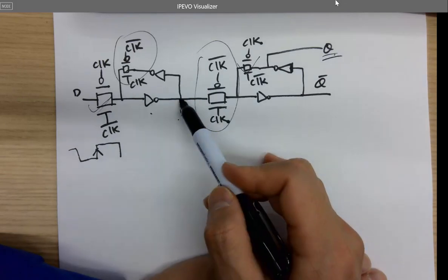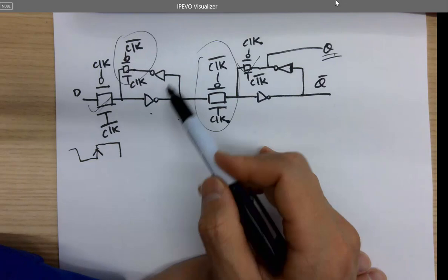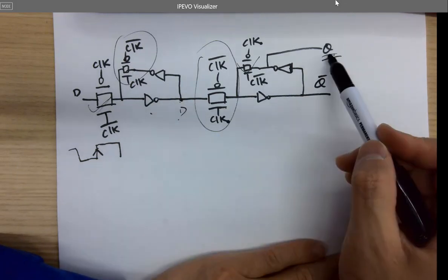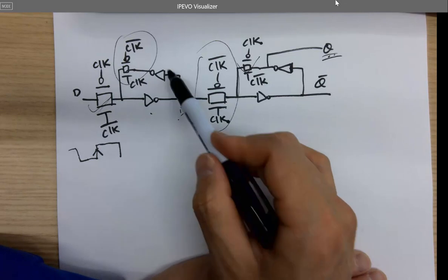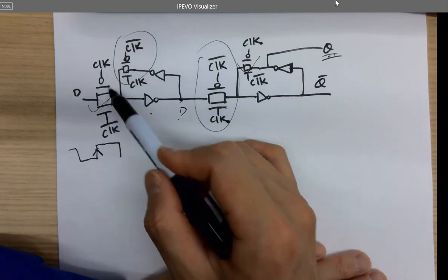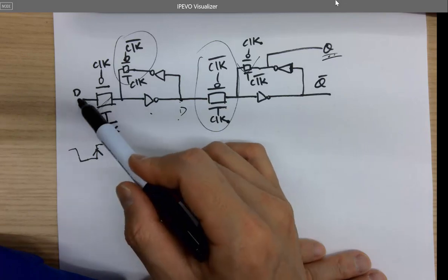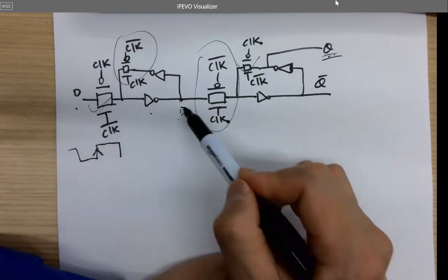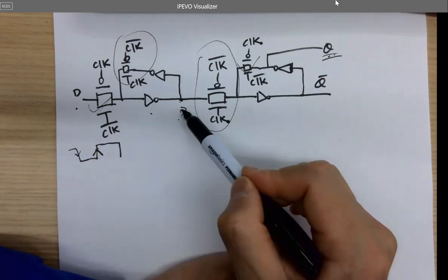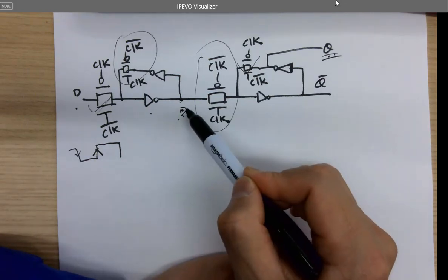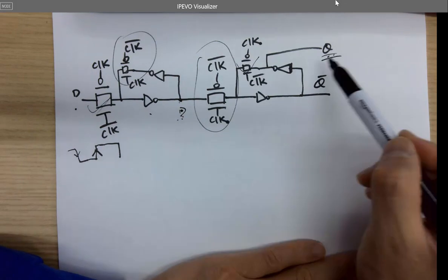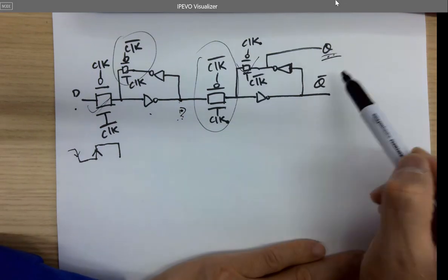So D will be stable here. D is being stored over here, it's not changing. Whenever it's being sent to Q, the rising edge is not changing anything here, so D will be stored over here. So we also want to turn off this guy, because we want the new Ds. That's a D being stored from the last falling edge. I'm going to store it here, and what's being sent to here is a stable D. It's a very stable D being sent to Q and Q naught.